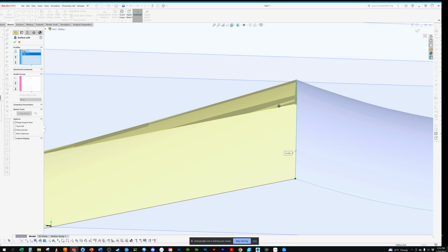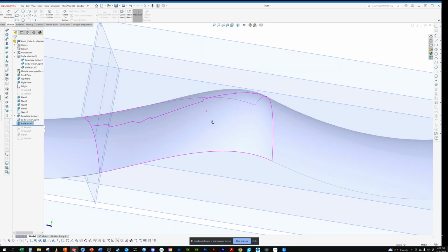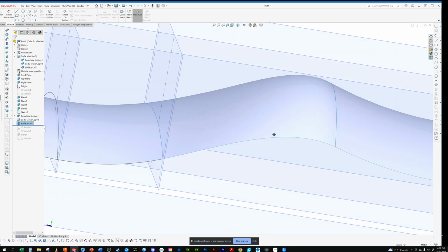It's easier to see. So we know that tangent is like a radius. It's making a smooth edge. We're going to come in and I'm going to say I want it to be tangent. And I keep grabbing the wrong one. End constraint. Tangent. There we go. So you can see now it's modifying that surface so that it follows this curve first and is making a smooth transition.